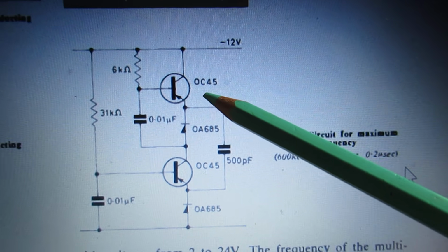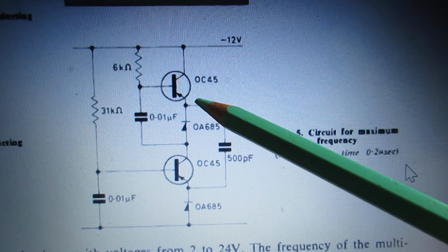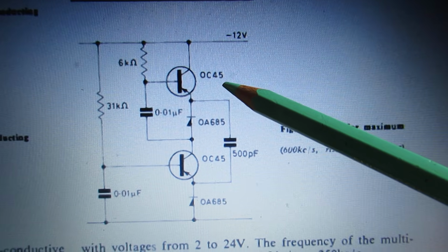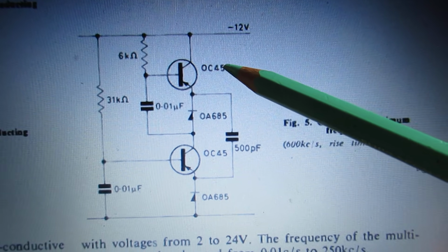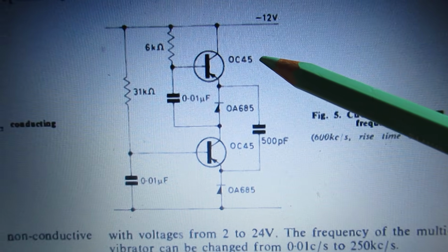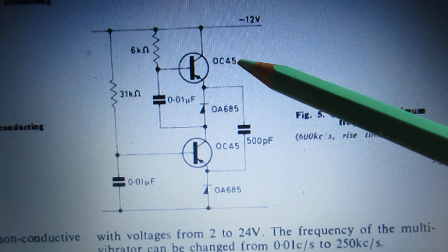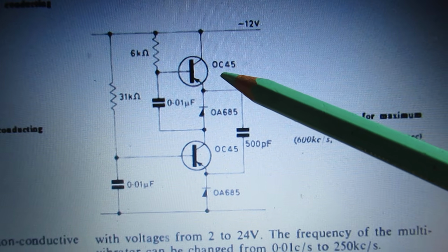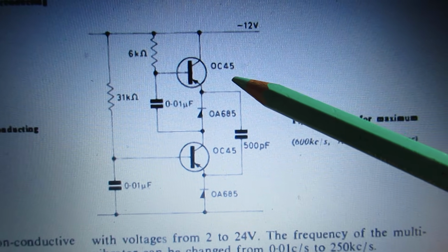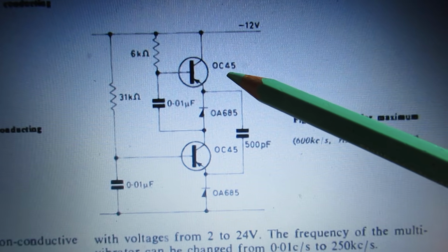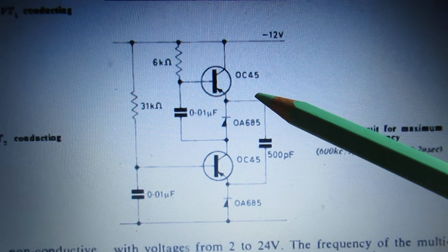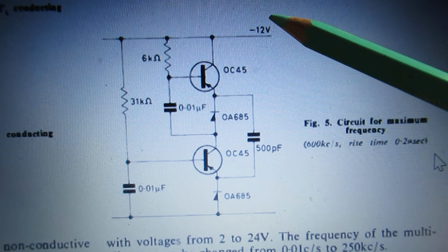And when you order BC547s in China, you will surely see that their current amplification is very high, in the order of 250 up to 300, while the old BC547s from Europe had an amplification factor in the order of, say, 150 or so. So that's something to take in account.